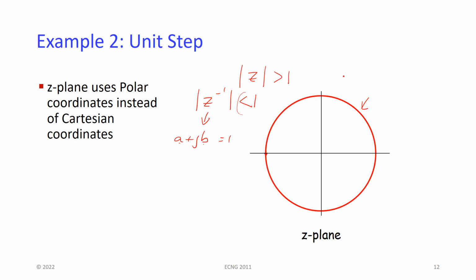Because we're dealing with another transform, like the Laplace transform was the S-plane, you plotted that, the S-plane had a real and an imaginary part. So the whole S-plane was the Laplace transform. If we remember, we can get some Fourier transform information by making the substitution S equal to j omega. Where is S equal to j omega?